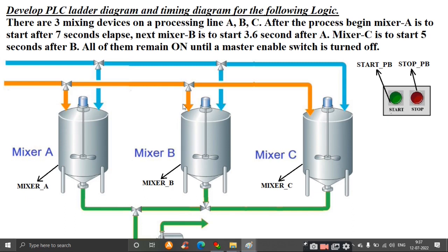Timers are built-in devices in a PLC. Timers count fractions of seconds or seconds using the internal CPU clock. Timers, when energized, result in the closure or opening of the contacts after some preset time. So the timer is thus treated as an output for a rung with control being exercised over pairs of contacts.